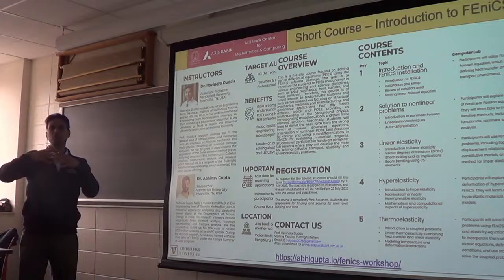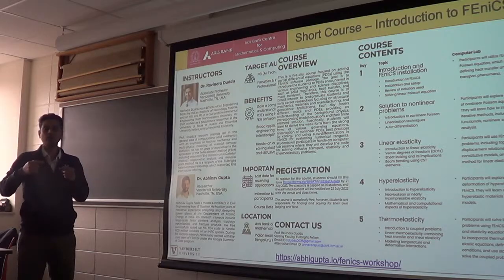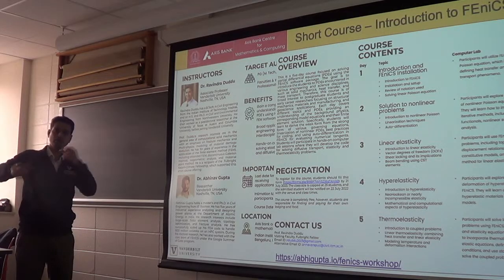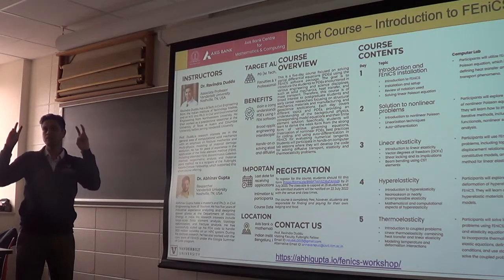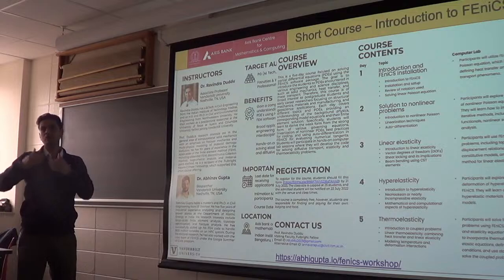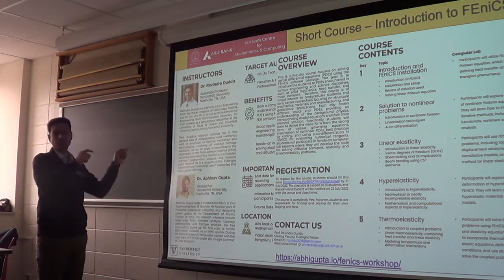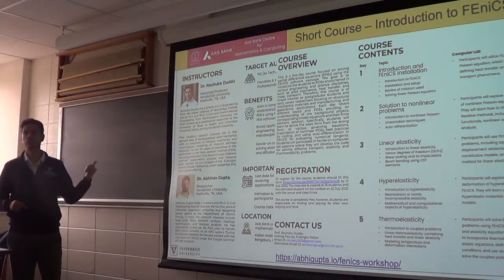And then there is a time step also, not just a spatial size scale, where we first solve it, then damage progresses a little bit, and then we have to resolve the problem because it's nonlinear. So we are doing several time steps where cracks are slowly propagating in time, even though there is no real time in the phase field equation that we used.